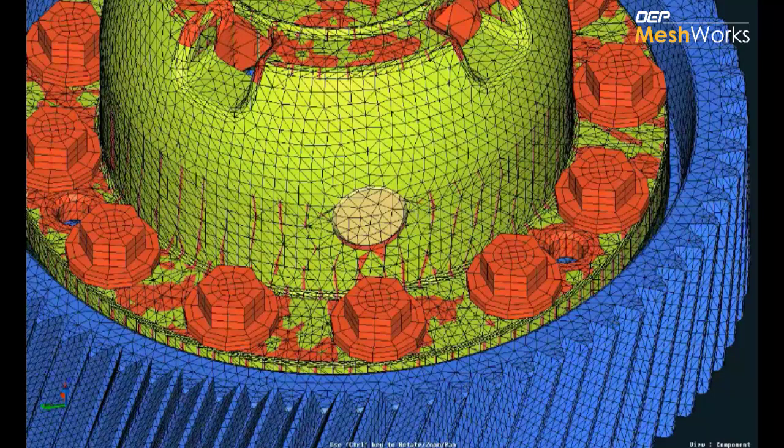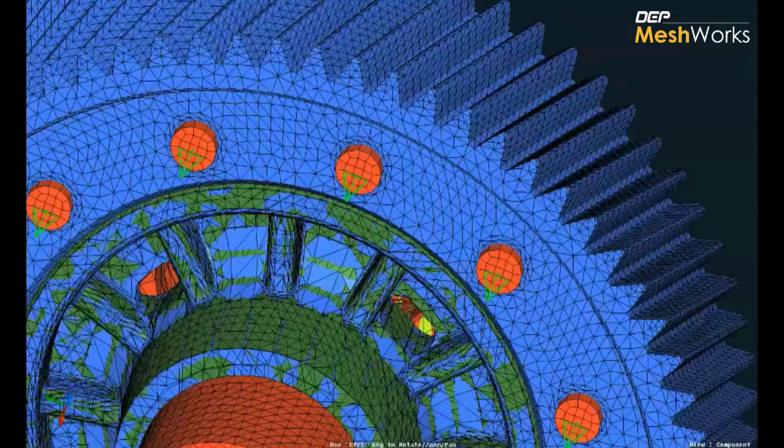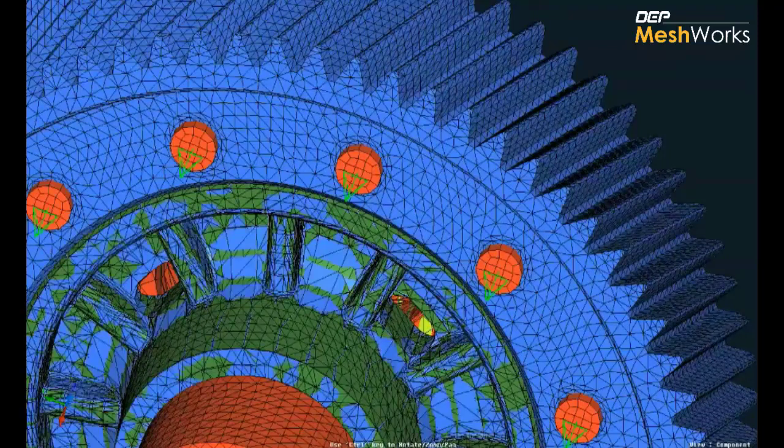The mesh type is going to be tetra mesh here, and I'm going to follow the same process for the other components as well. Here we have a fine mesh as the current part, and the new part is going to be a coarse mesh, again an FE part, accept, and the mesh type is going to be tetra mesh. That's all, it's been saved.